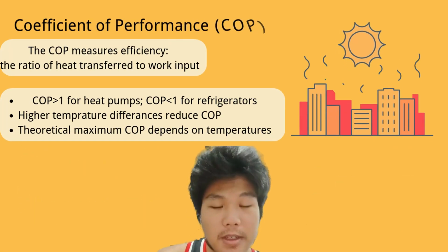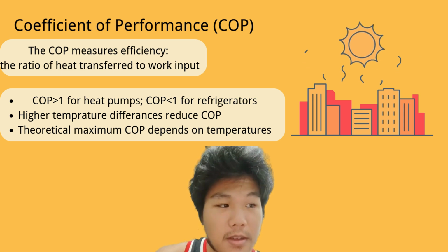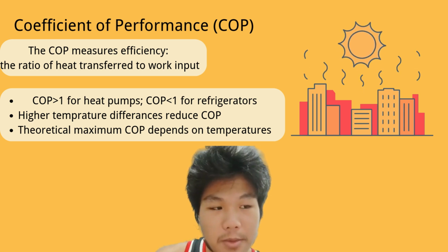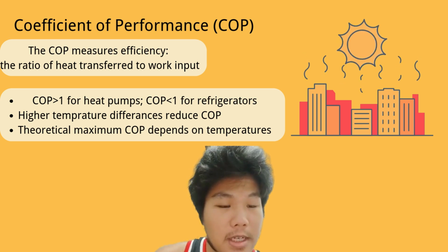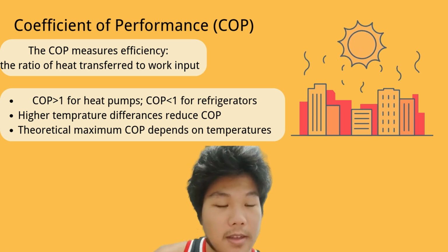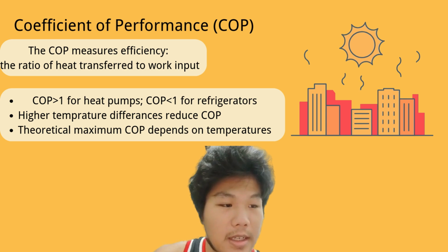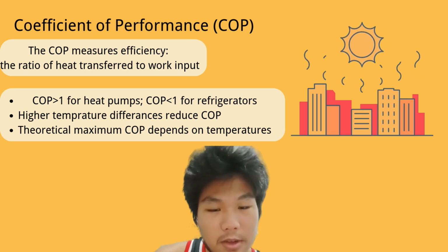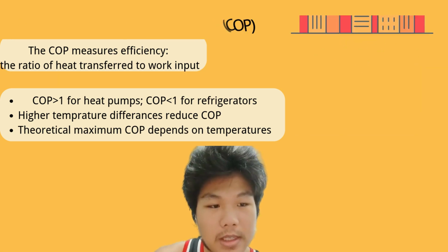As for the coefficient of performance, also known as COP, the COP measures efficiency, which is the ratio of heat transferred to work input. And there are 3 key points of it. First of all, the COP is greater than 1 for heat pumps and is greater than 0 for refrigerators. Secondly, high temperature differences reduce COP. And the last, theoretical maximum COP depends on temperatures.